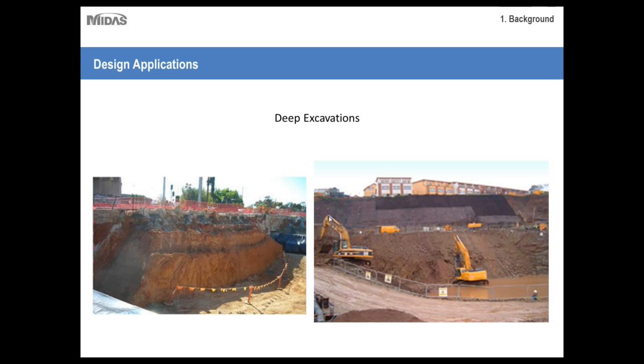And then naturally, deep excavations. Whenever excavations for foundations are created, slopes are a natural part of creating these foundations. Until these foundations are built, the stability of these slopes needs to be checked and designed for. Oftentimes there are tiebacks or soil nails that are installed into these slopes to support them. But depending on the type of soil, the soil to the left here is actually very clay soil. As you can see, it can stand very firm on its own as long as it's not too high. So that's another important design consideration: the type of soil that you're excavating into.